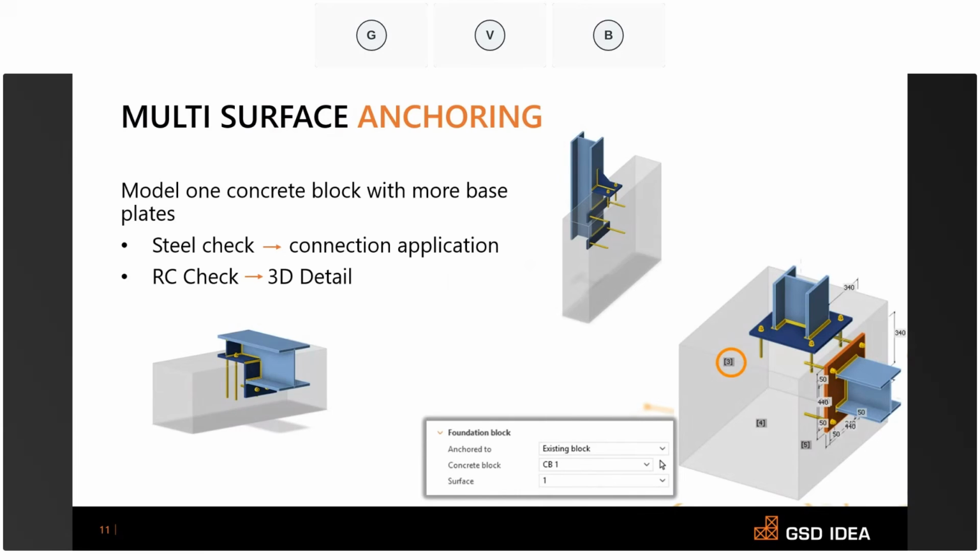This means that you can analyze different arrangements and also the load transfers within the same foundation block in the connection application, and from there, as usual, import it to the RC check option, and import it to the 3D detail to completely check the pedestal.